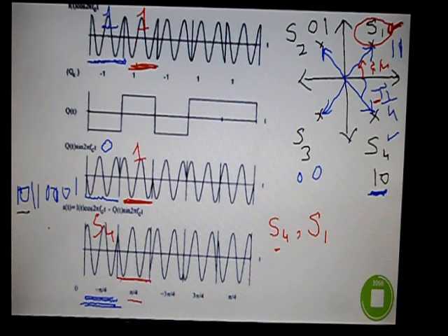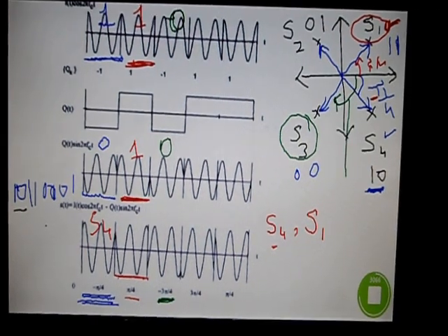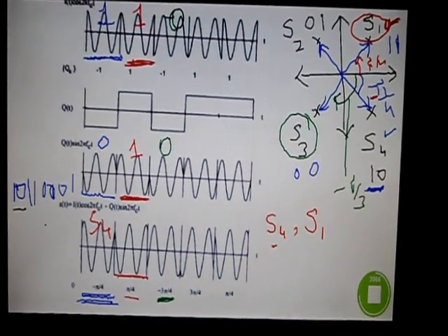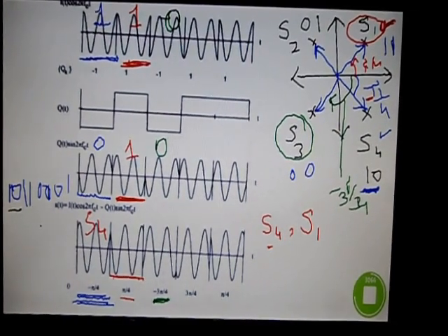Now, in a similar way, you can observe other waveforms. See this, you have a minus 1 here, a minus 1 means a 0 here in this third period, and you have a 0 here as well. So whenever you transmit 0, 0, S3 should be transmitted, and you can see that S3 has minus pi by 3 phase angle. Sorry, not minus pi by 3.